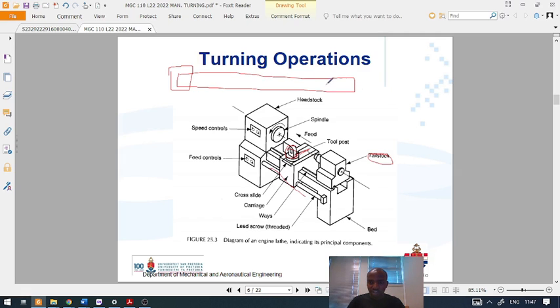Here the rotation center will only have a center 0 with no displacement in the radial direction. Here, on this part of the component, you are going to find a bigger rotation, so you want to balance it out with a tailstock so that it can remain concentric during rotation.